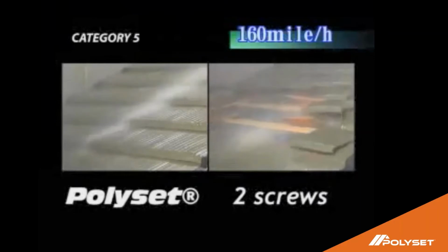As you saw in the video, on the left, each of those individual tiles is adhered with a patty underneath. What that means is later on down the road, if somebody were to walk on that tile, whether it's a pressure washing company cleaning the mold or the mildew off, or somebody doing some roof maintenance, all those surrounding tiles act as an individual system because they still have that patty underneath.